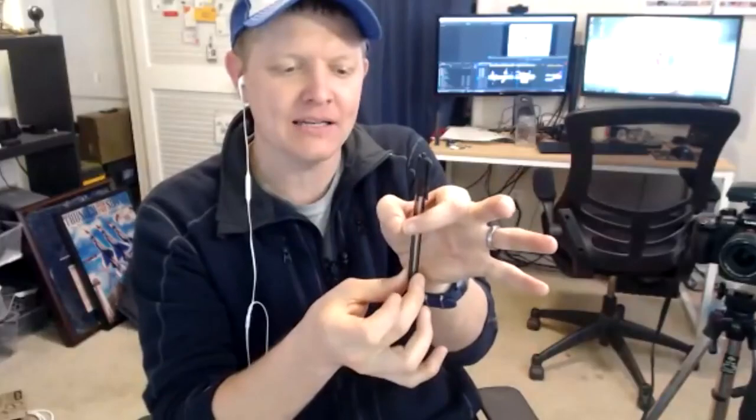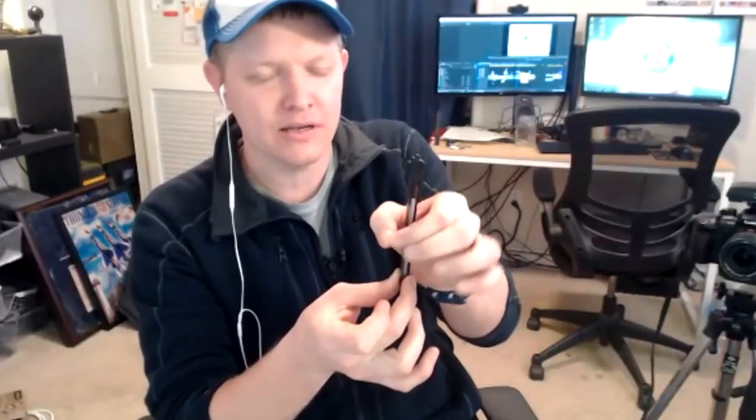And you bled off a little bit of it and shot it to the side so you could counteract the spin. Right. So let me ask you this. If the LLTV had the jet engine going up through it like that, then you had a certain attitude that you could roll to before you would, plus or minus 40 degrees in pitch and roll. 40, so that you would gimbal lock, so to speak, after that. Yeah, we have pitch and roll gimbals.